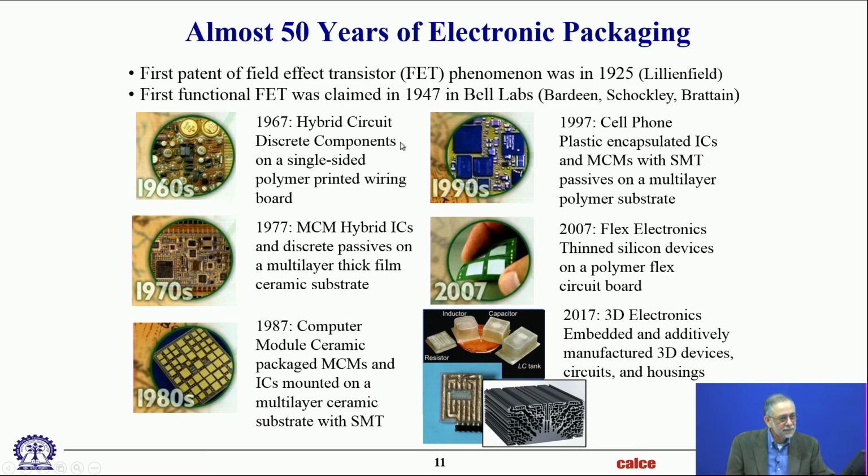Did we add any new things to make it work? We actually did, but interestingly, it was not on the electronic side, but the boxes. The mounts for the boxes had fatigued. You could see fatigue cracks in those. So it's only the externals that we had to change. The electronics we never had to change.